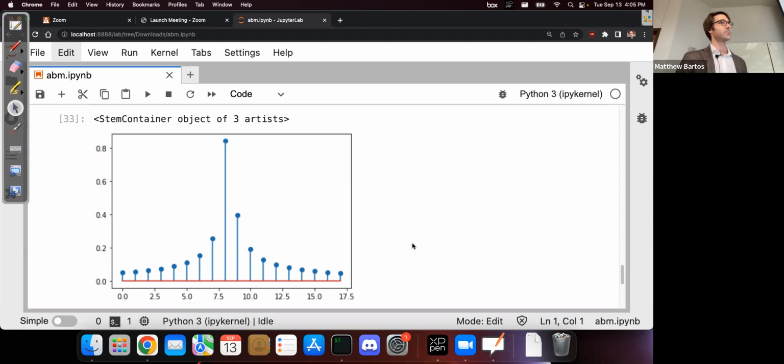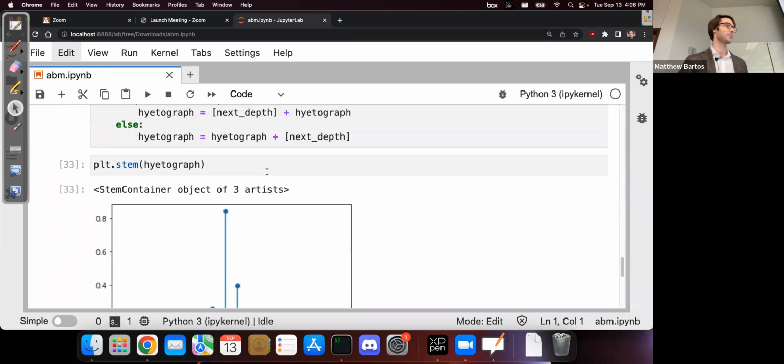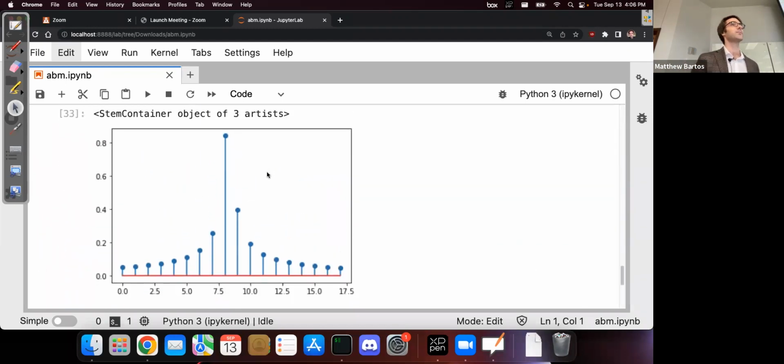So you don't have the data for time? Yeah, we have from our IDF relationships the total depth of rainfall that would fall and the duration. So we can create a realistic looking rainfall hydrograph that matches those parameters using this method. Yeah, so it'll generally look more like this than this. Okay, cool. Are there any other questions?